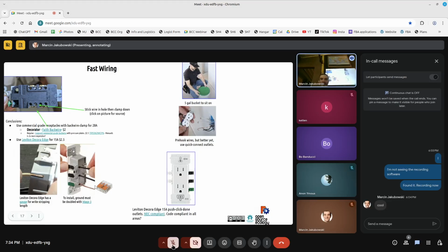So the industry standard is wire nuts, these caps that you spin. First, you cannot connect solid to stranded; it's very hard to do that. Second, it takes more time. Third, you damage the wire by screwing it on tightly. So this doesn't damage it, and it passes all the codes for conductivity and thermal performance.